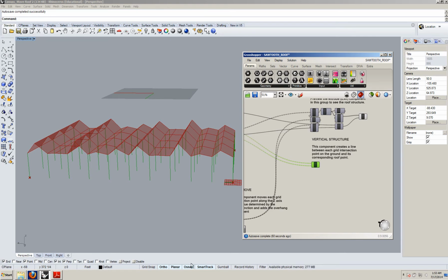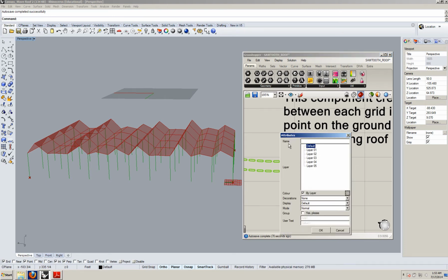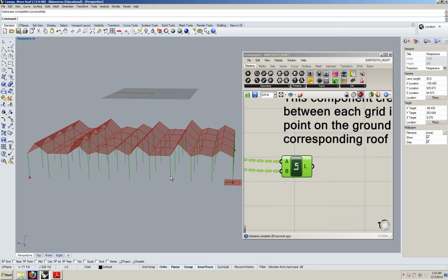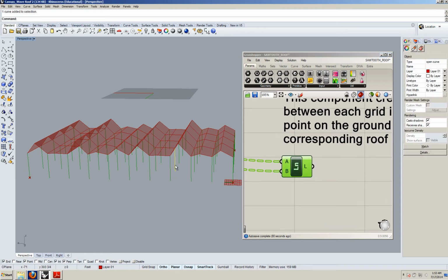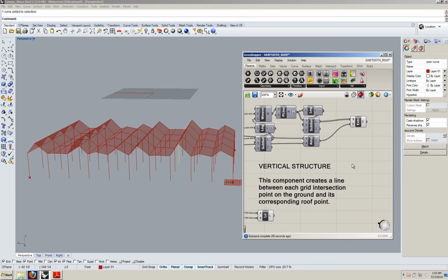So as you know, what you would do at the end of the day when you're set with your design after you've finished adjusting things is take the components that you want to create in Rhino, or to bake into Rhino, right-click on them, click Bake, and you would likely have your file set up so that it had essentially a columns layer and a panels layer as the start from Grasshopper, and hit OK. And then those lines are now in Rhino, and you can start to edit them or use the pipe command, P-I-P-E command, to create a dimension around them, and I'll show you that in a second.